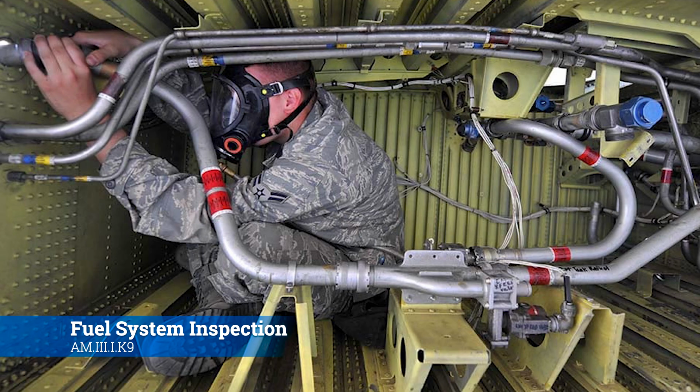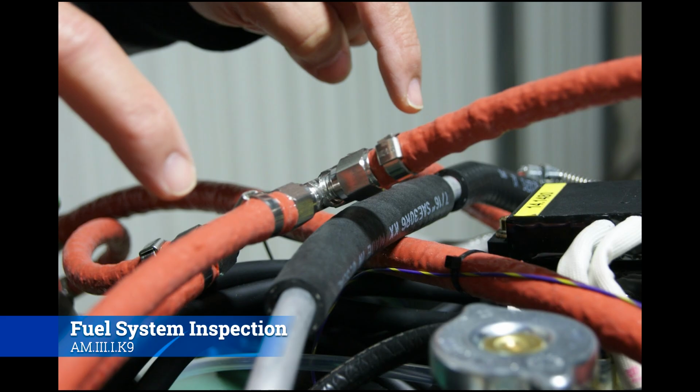And so making sure that the fuel tank on the inside is 100% correct is absolutely critical. Okay, you're also going to want to check and make sure that the fuel lines are in good working order. You're going to check all your torque stripe. And the big thing with fuel lines is make sure that they don't rub on anything. They are really prone to chafing, and chafing almost always will lead to some sort of breakage in the line.